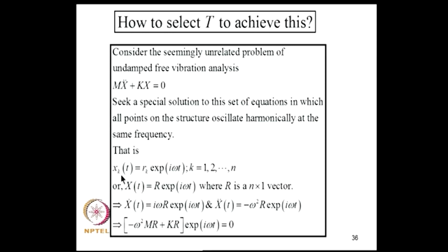That means, if you take the ratio of displacements at two different places, that ratio will be independent of time. So, the motion will be synchronous, all the points reach their respective maximum and minimum simultaneously. So, any 2 points on the structure would be either perfectly in phase or perfectly out of phase. There are no intermediate phase differences possible.